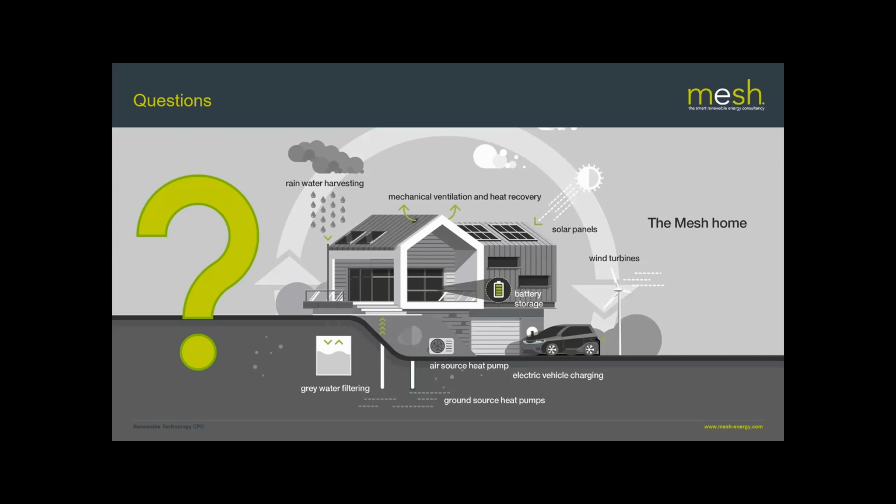But our experience is that it makes sense if you have a building which has an air tightness of 3.5 or better, and between 3 and 5, it's going to be a bit marginal. And if the building's less airtight than 5, then you really probably need to be thinking about improving the airtightness of the building before considering MVHR.